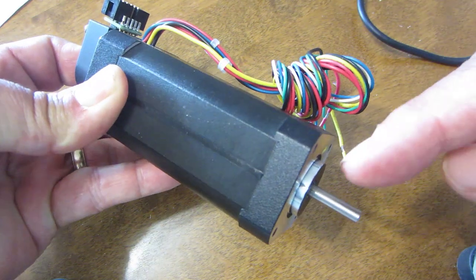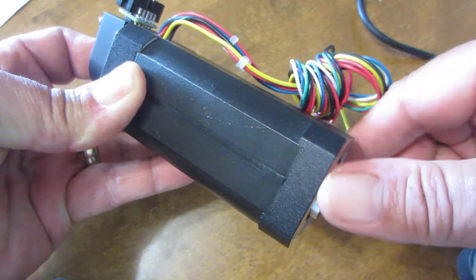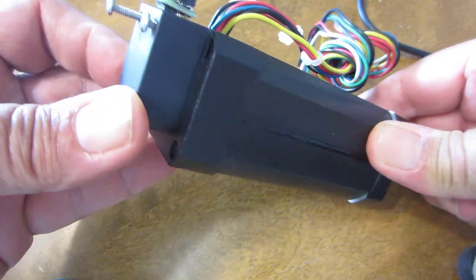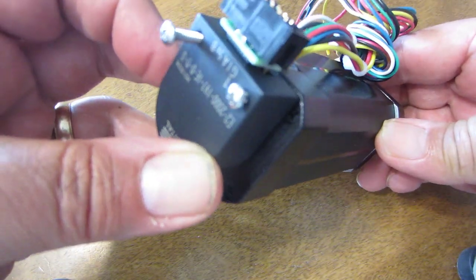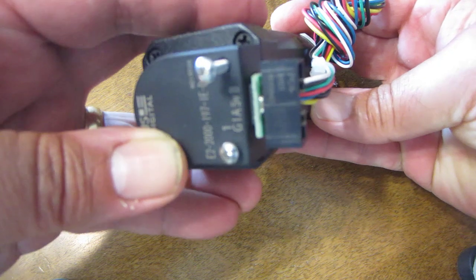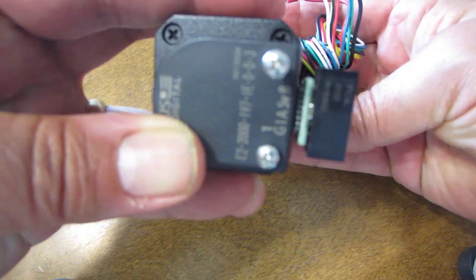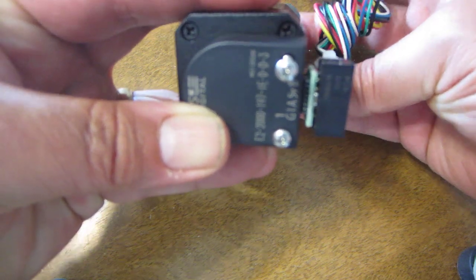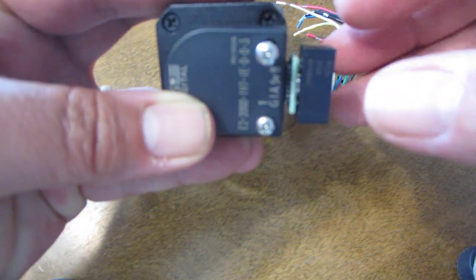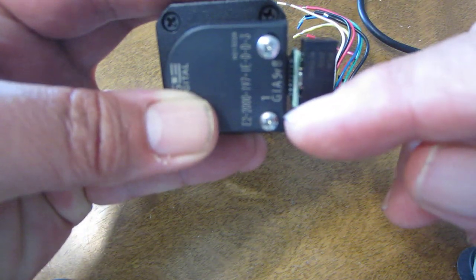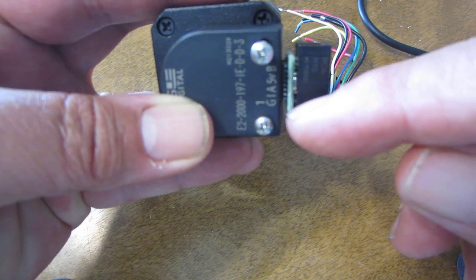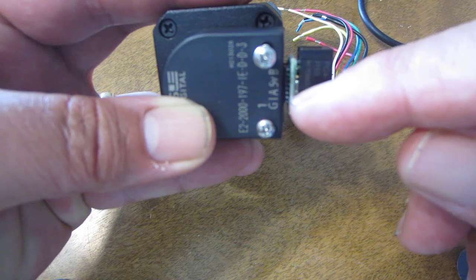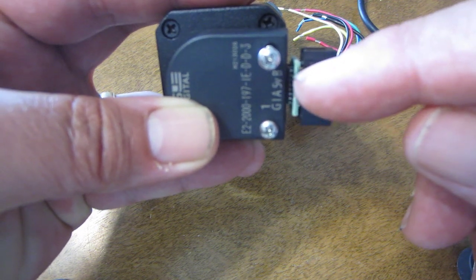Here is a servo motor. You see the motor shaft here quite clearly, and it's actually what's called a double shaft motor, and on the other end of the motor we put a motor encoder. The motor encoder is a US Digital motor encoder. It's a 2000 line motor encoder, and you can actually see the pinout. You can see the pins off the encoder: you have ground, the index, the A channel, 5 volts, and then the B channel.